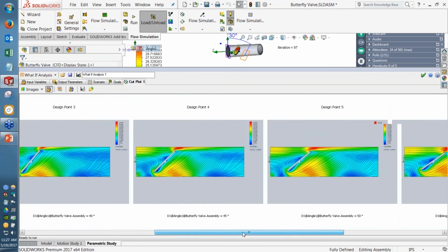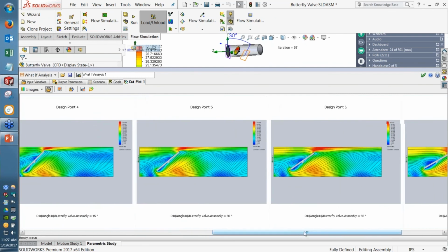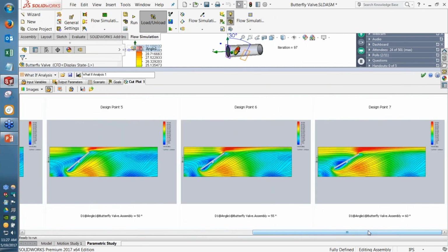Of course, I probably have some sort of curve that I want to meet. That's part of my product requirements. But the secondary part of that question is, where would the valve actually be? You know, what position would it have settled in if it wasn't fixed in place? Well, if I know what the mass of this valve is, I can probably guess at what sort of the torque on the valve is under its own weight.